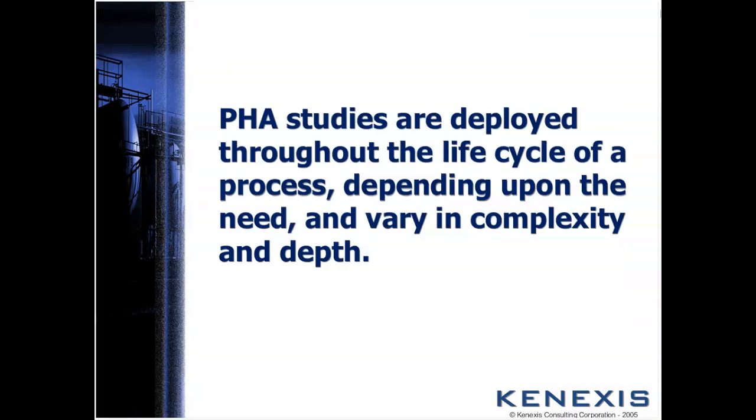Okay, let's explore this in a little bit more detail. I said PHA studies are deployed throughout the life cycle of the process, depending on the need, and they vary in complexity and depth. So you've got an early crude analysis on some P&IDs, maybe that's all you've got, and then you've got a full study into detailed design.